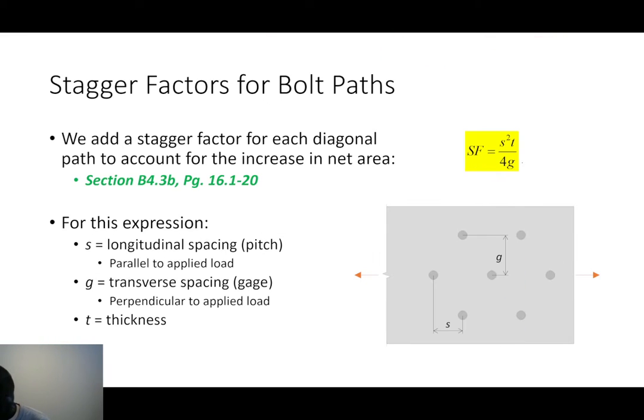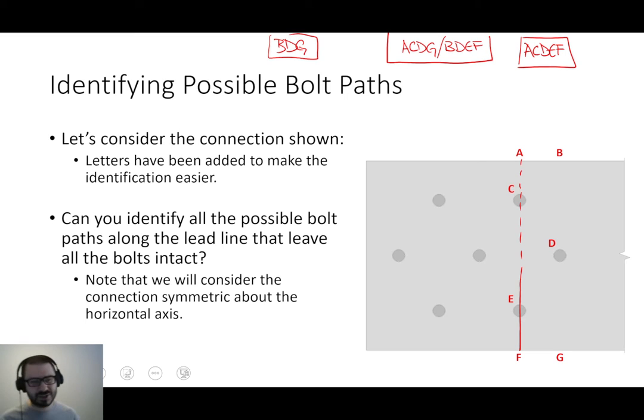Imagine taking a pair of scissors, and imagine this was a sheet of paper, and actually cutting through the plate along that vertical line. Now if you did that, yes, you'd cut the plate in half, but can you move it away? Well, no, because this bolt right here is still pinning that right side of the plate. So in order for this right half of the plate to translate to the right, that bolt D has to shear off.